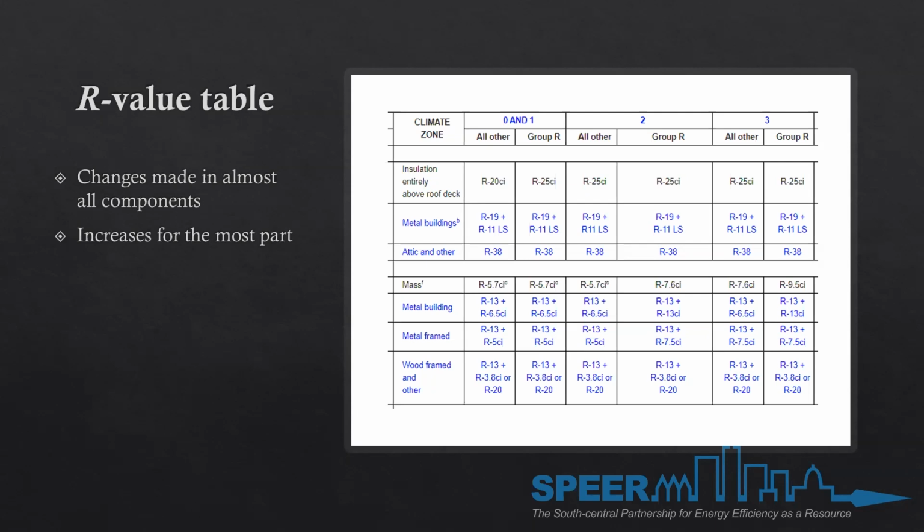Most buildings are required to have freeze protection heaters. Yeah, that's another one that came up. We found these buildings to be conditioned due to energy use. Absolutely. So if you're just doing sprinklers only and you're putting in a heater to keep it from freezing, depending on the size of the building, you may run over that energy usage, and now it's considered conditioned.